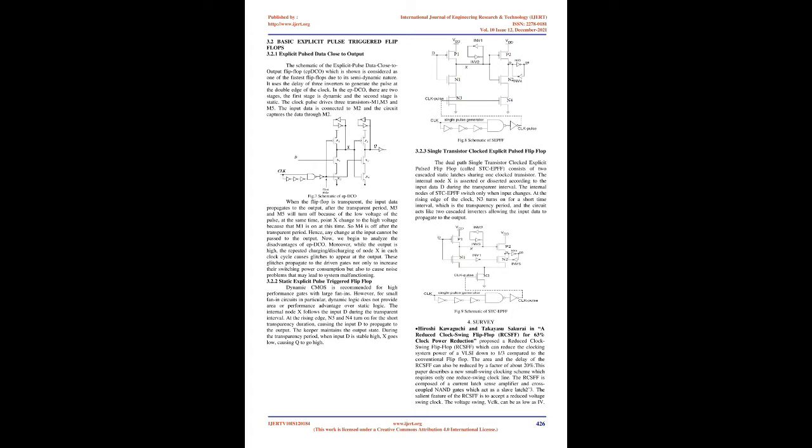The effectiveness of the clock slope optimization is discussed in detail for the existing classes of FFs. The impact of such an optimization in terms of additive skew and jitter contributions is discussed, together with the analysis of the impact of technology scaling. Extensive post-layout simulations on a 65 nm CMOS technology are performed to check the validity of the underlying assumptions and approximations. In this paper, the impact of clock slope on the speed performance and energy consumption of a wide range of FFs has been discussed.